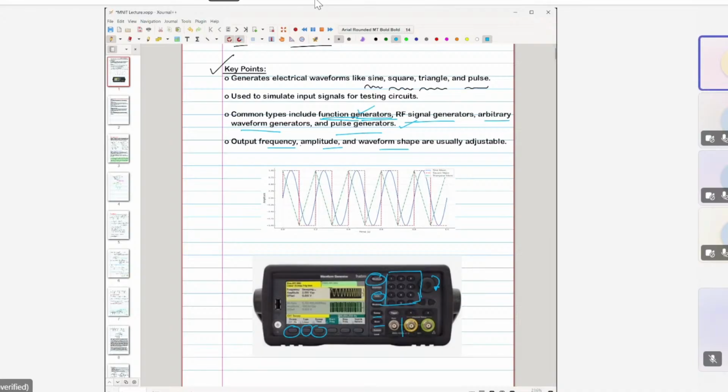You can see here there are two channels provided. So this is channel 1, this is channel 2, and these are the BNC connectors. So you can use the BNC connector and take the generated waveform from here and use it for your purpose. And if you check carefully in a practical signal generator, you will see one resistance written here, that is written as 50 ohm. This 50 ohm is very important, this is the matched load, right? So this should be there, 50 ohm.